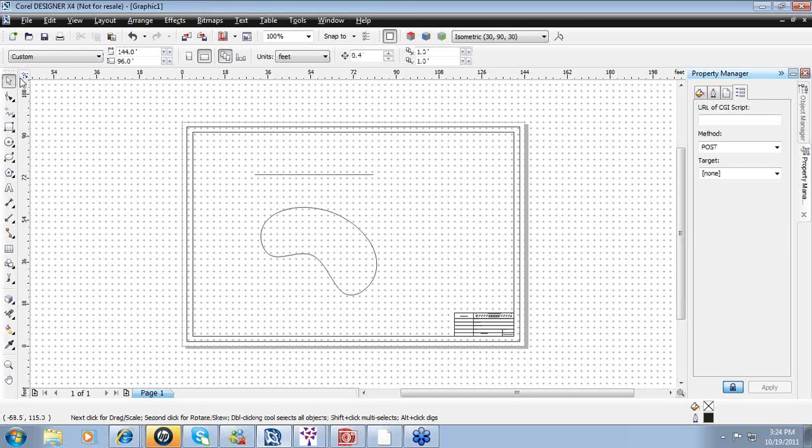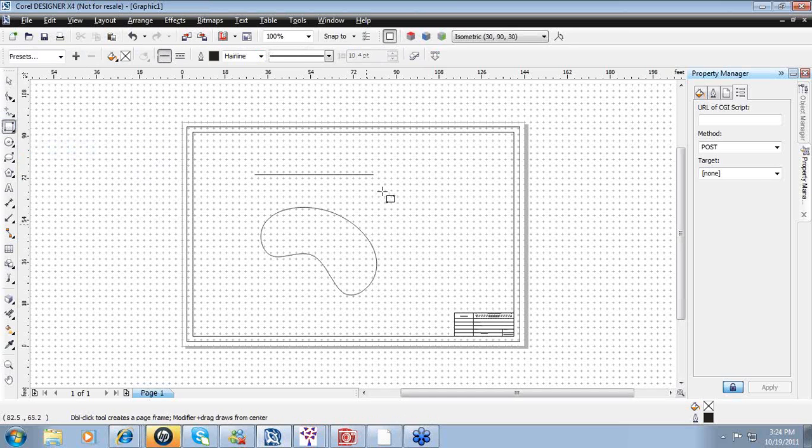Additional tools that are available within the EARTHSCAPES program, and just some basics for you to work with. We do have your geometric shapes, rectangles, as well as circles. If you are working with a basic landscape design, maybe this is a commercial property, maybe this is a basic foundation planting that you've been requested to design, it would not be unusual to use the rectangle tool and to simply left click and drag out a rectangle.